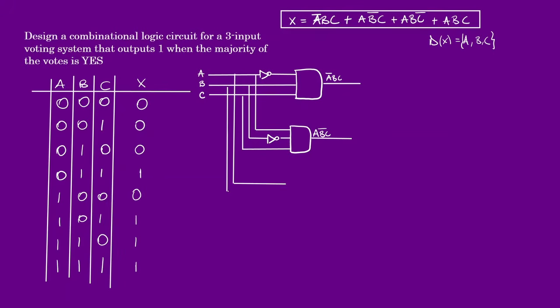So we have A, B, and we're negating C, so we have to keep that in mind. We negate C right before we lead it into the NOT gate. This is our negating symbol, a triangle with a NOT bubble, and this will feed into the 3 input AND gate. A, B, not C. And finally, let's extend this backwards so we have space.